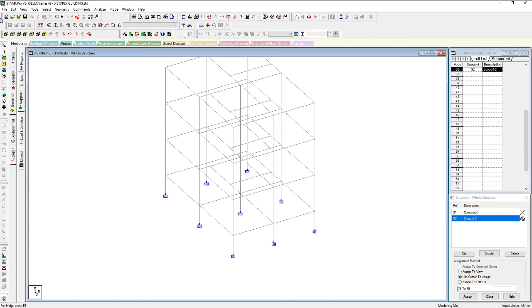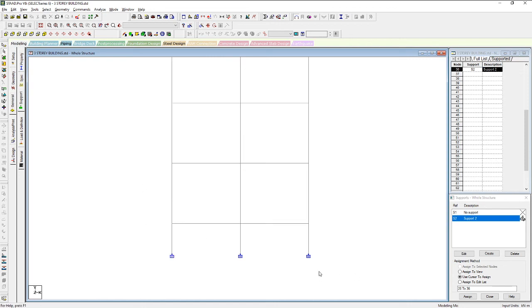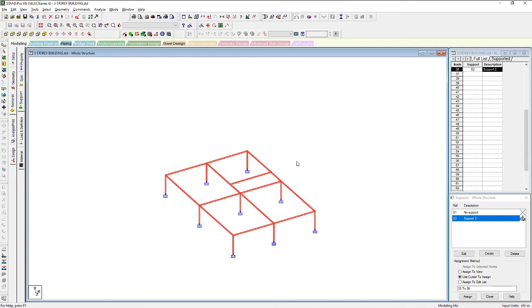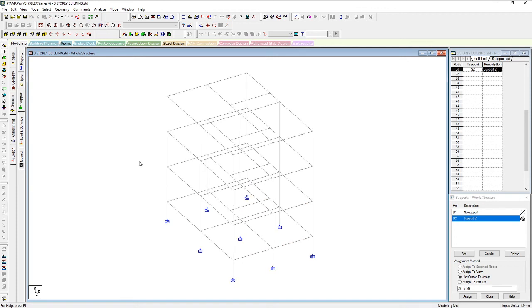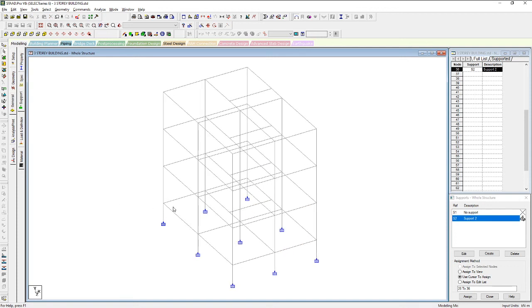So all you need to do is just like I did, highlight some of the members you want to see, and then go to your view, then view selected objects only. So it makes easy. Now, so let's check if all the members started from the 0.